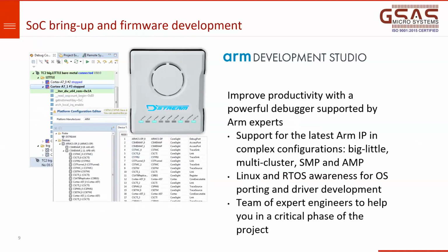Okay. Next is SOC bring-up and firmware development. Now you have tested the code on the simulation model. When the hardware is ready, when your SOC is ready, you have to test your code on the actual hardware. For firmware development, we use ARM Development Studio, which is a Keil-based IDE. I'll talk about the IDE when I come to the practical demonstration. With the help of ARM Development Studio, we'll develop your product code, whatever software code, and you test it on your hardware. To get that particular SOC up, to make whatever code you have written work faster on your SOCs, we use the DStream debugger.